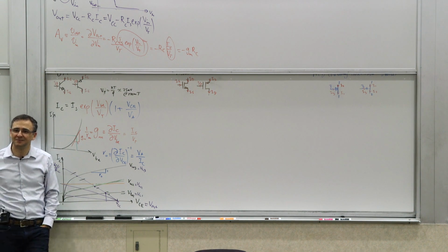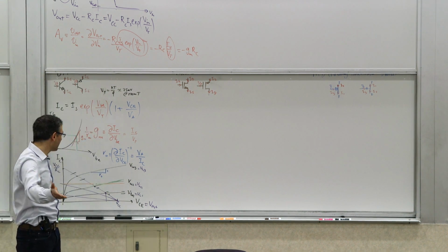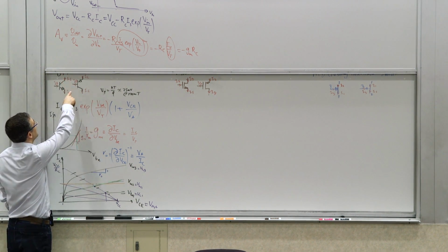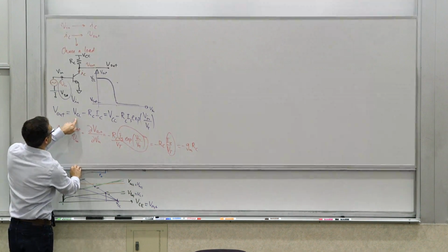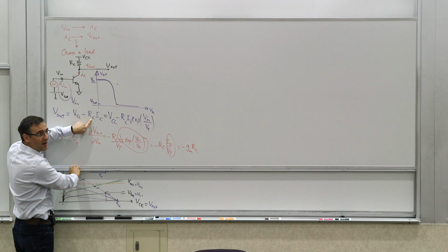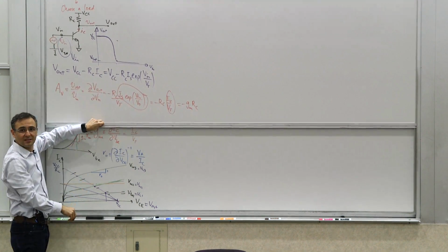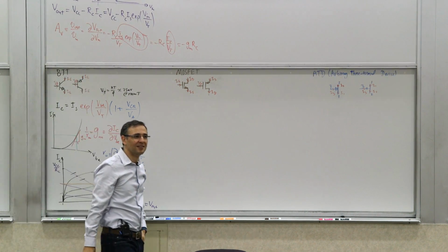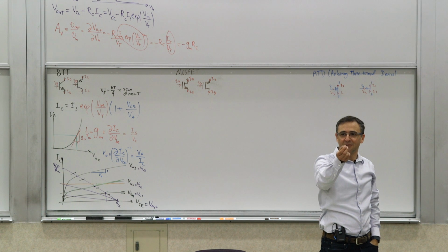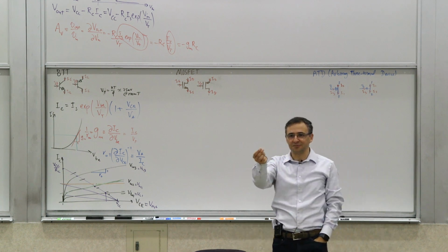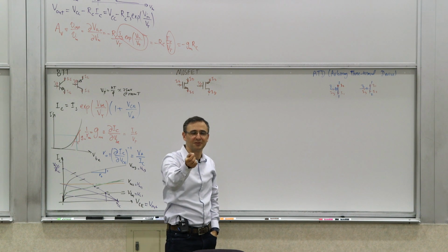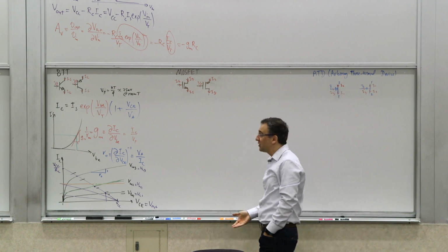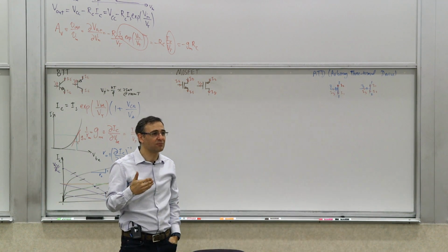Yeah, it would necessitate a negative resistance, right? Because remember, this slope is the resistance in the load line because it's referenced to the VCC. So it's the VCC minus that. So a line with a positive slope would correspond to a negative resistance. Now, obviously, you can't go to the stockroom and buy a negative resistance. Component values start from positive values, or at best close to 0, right? They don't have a component of -1, -2, -3, -4, -5. But you can make circuitry that actually behaves that way.